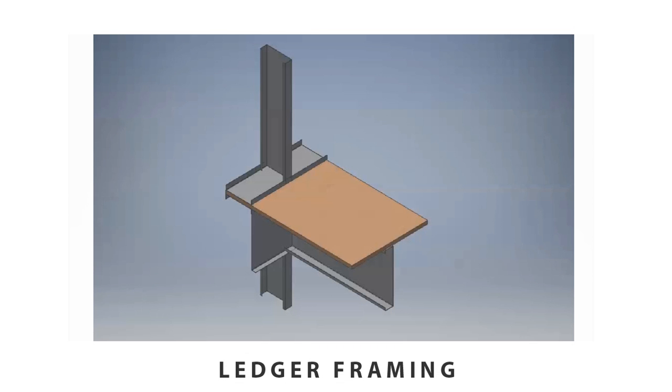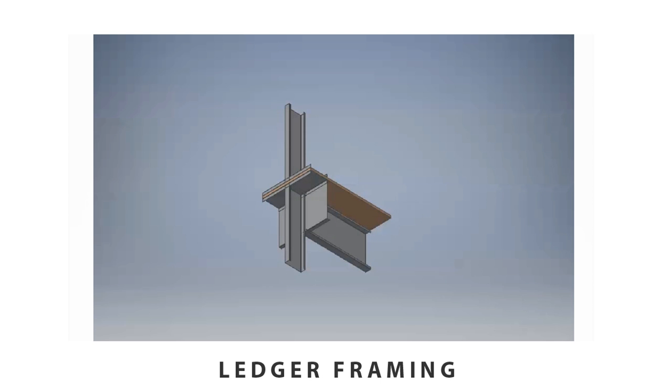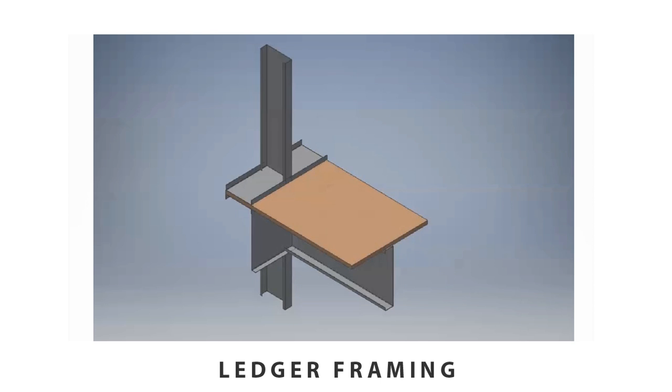Typically, cold-formed steel structures are ledger framed, where the wall stud below meets the floor line and the joist frames into the side of the stud, creating eccentricity on the stud. The default setting applies an extra end moment to the stud. The triangular moment diagram, produced by any eccentricity, is added to the parabolic moment diagram that results from wind and seismic transverse loads.